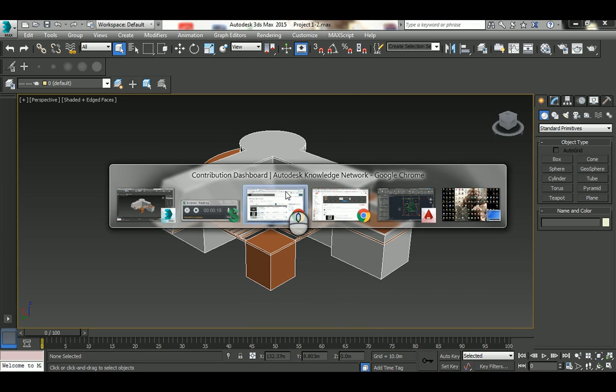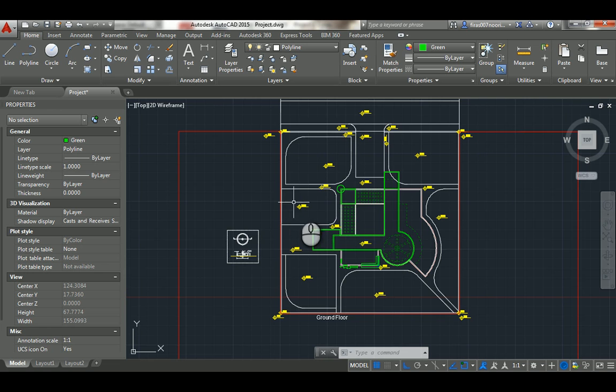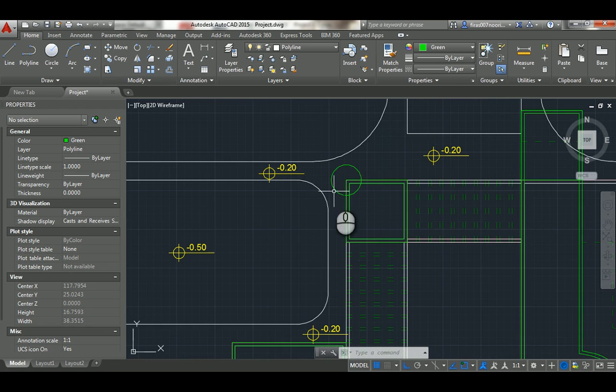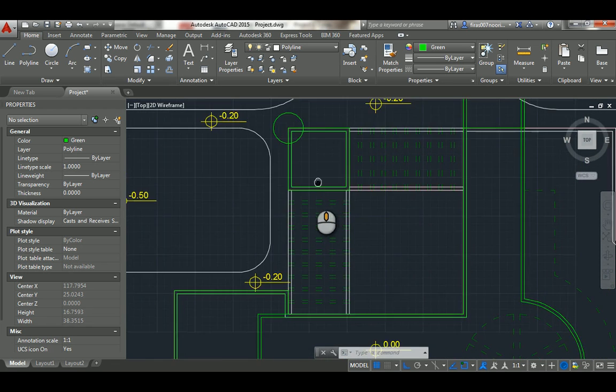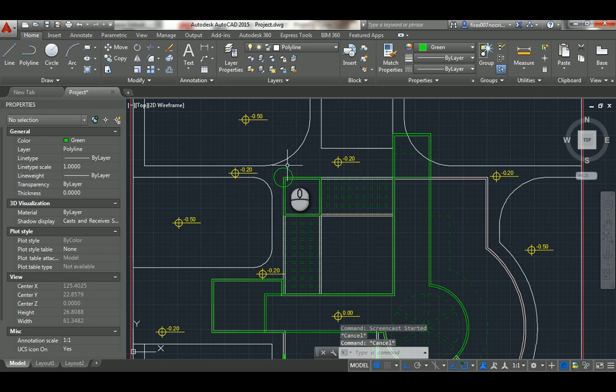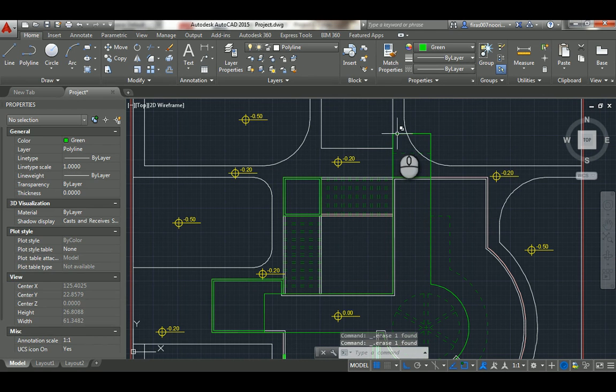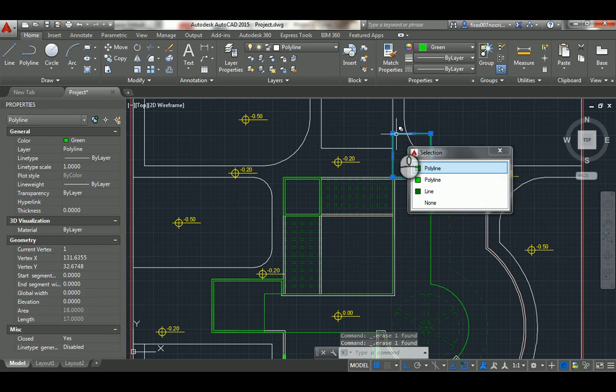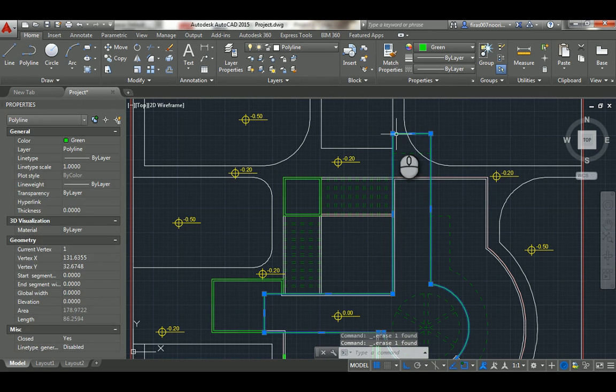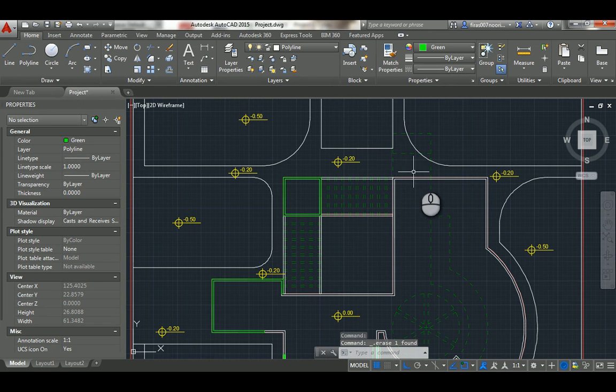So I'm going to go to AutoCAD, and it's a good idea to turn off any layers that might conflict with your work, or sometimes delete extra elements that you don't need anymore, like these double lines that I made for the wall and the extra rectangle for the small bits of slab here. I will turn off the hidden layer as it might conflict with the walkway.